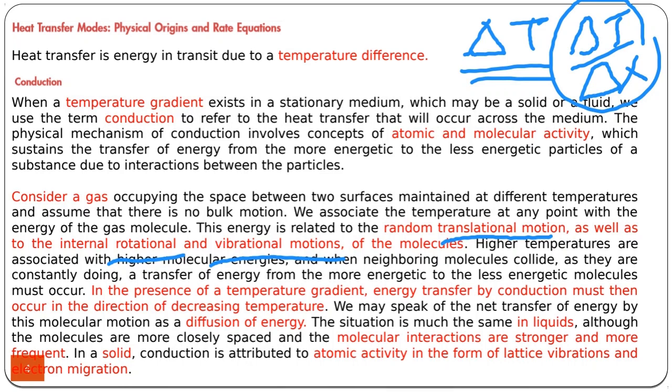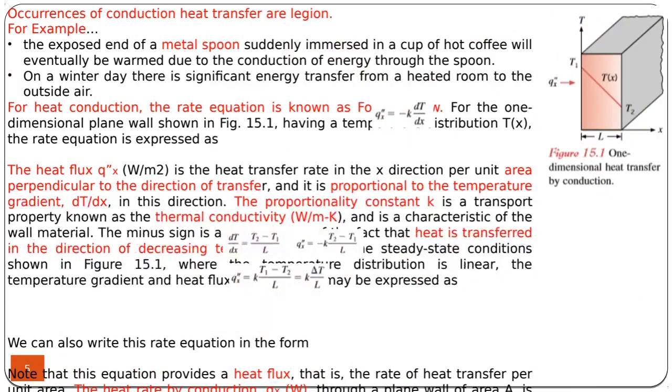In the case of solids, it's because of the lattice vibration of the solid construction. Otherwise, if it's gas or liquid, it's because of either diffusion of the energy between the atoms and molecules or bulk motion of the fluid. In this case, it's actually called convection, but in any case, part of the convection is conduction.